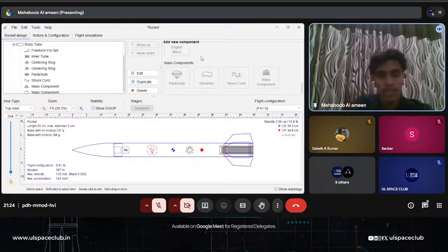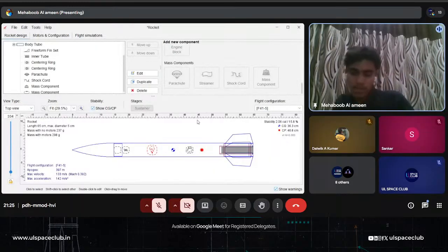If I select the second parameter, position, and I need the apogee, the maximum value, and I come down here, we can also give a minimum stability. We can give some parameters right here, which may change the maximum or minimum values. Okay, then come here and start optimization.